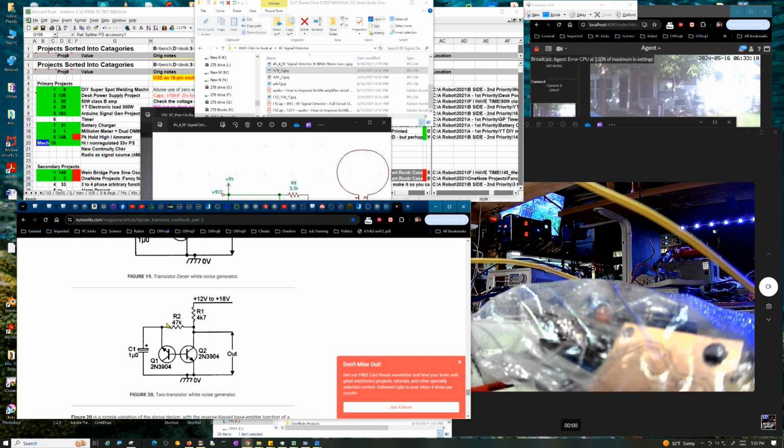So you look at this thing and think, well, this will never work. Even the lowest leakage diode in the world, you're going to try to amplify it in a transistor. Well, it's not used that way, because you also know a bit about transistor data sheets. These base emitter diodes are usually limited to about a 5 or 6 volt reverse breakdown. So this is actually acting like a 5 or 6 volt Zener diode. The whole key is Zener diodes get real noisy when the current is real low.